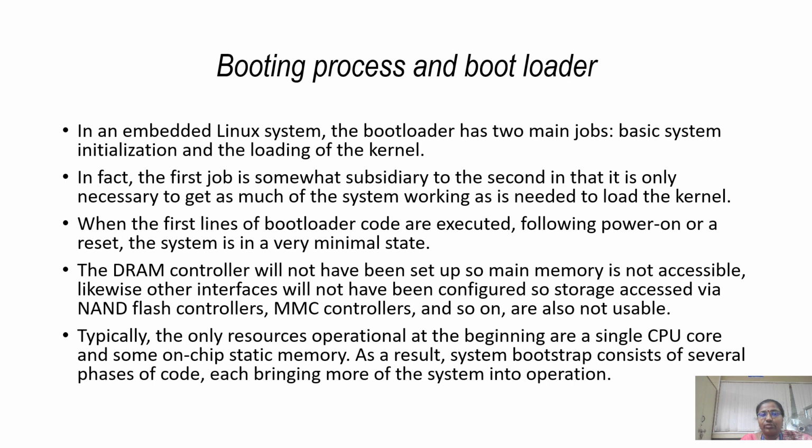When the first lines of the bootloader are executed following power on or a reset, the system will be in a very minimal state. The DRAM controller will not have been set up, so main memory is not accessible. That is your dynamic RAM. Likewise, other interfaces have not been configured, so storage accessed via NAND flash controllers and MMC controllers and so on is not available. Typically the only resources operational at the beginning are a CPU core and some on-chip static memory. As a result, system bootstrap consists of several phases of code, each bringing more of the system into operation.